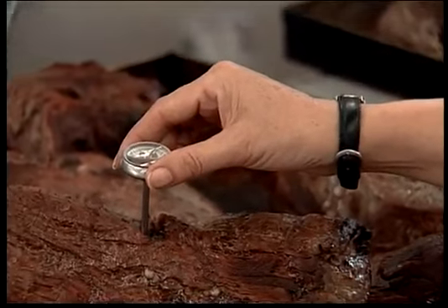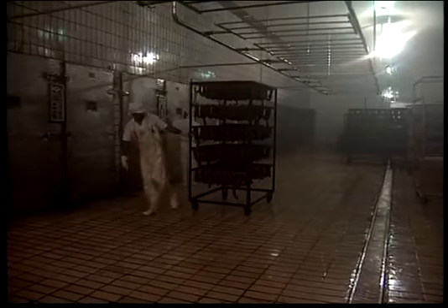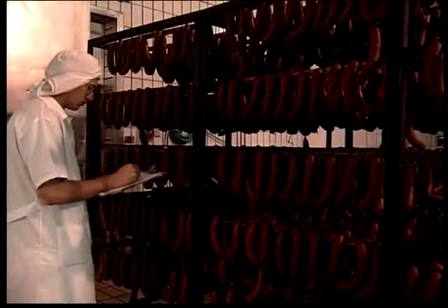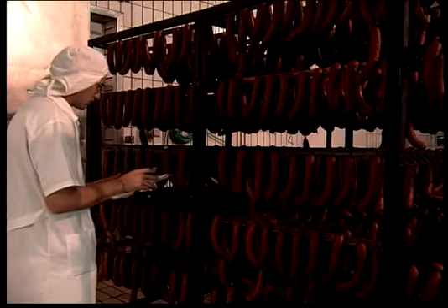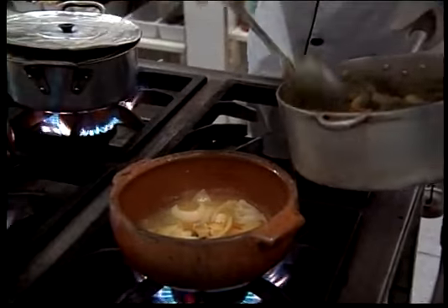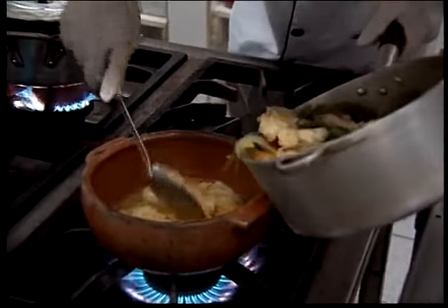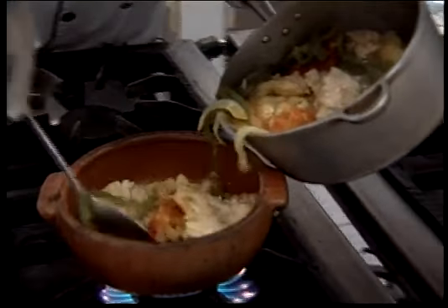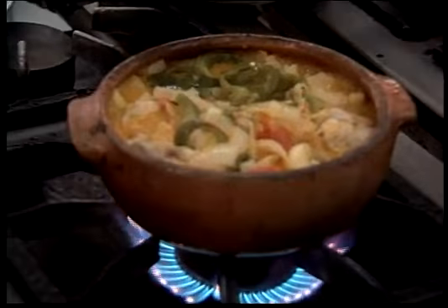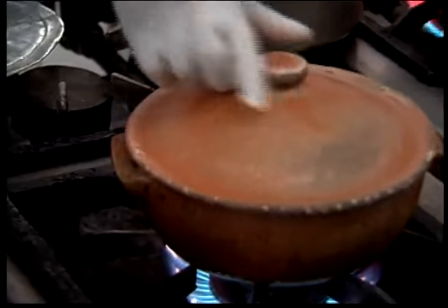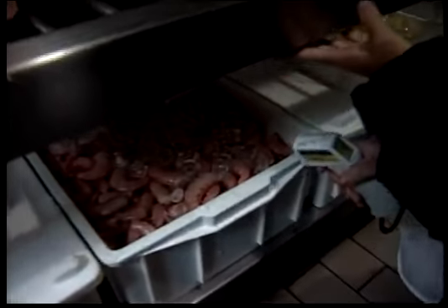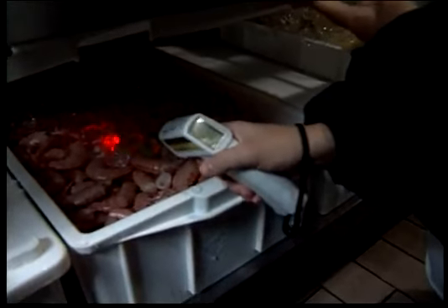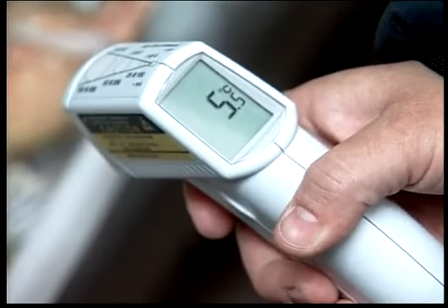Temperature control systems must take into account the nature of the food, that is, its water activity, pH, and possible types and initial microbial load, the shelf life intended for the product, processing and packaging methods, and how the product is to be consumed, that is, whether it needs further cooking or is ready to eat. The variation tolerances for time and temperature must be specified. Temperature records must be checked at regular intervals and evaluated for accuracy.